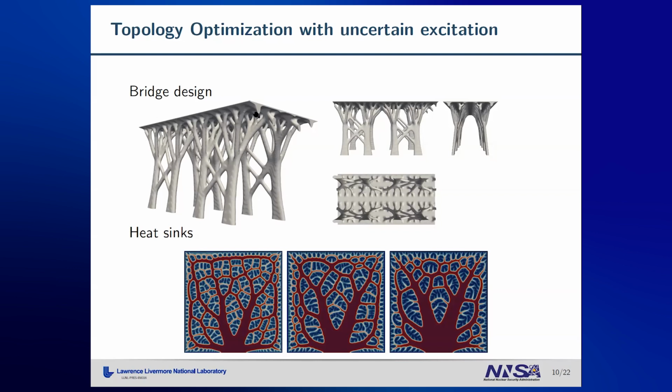However, being able to model these fast oscillatory uncertainties in the excitation or in the geometry actually allows us to approach real problems. Until now, we could have done this with Karhunen-Loève expansion, for example. However, we cannot actually account for this fast oscillatory uncertain excitation or model fast oscillatory random processes. And here is a further example of the heatsink design with a very fast oscillatory random excitation as well.